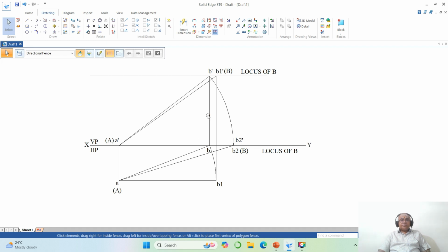Now you need to show the thicknesses. Just go to shift, select this line and the front view and top view line, make the distance 0.5, then you select the true length line, select this line and this line, you make that as 0.35. So then you come down to this, you click on this and you make this line 0.13 because that is the XY line. Now we go to split this line till here. Okay, so we have the XY line, you just go to remove this.